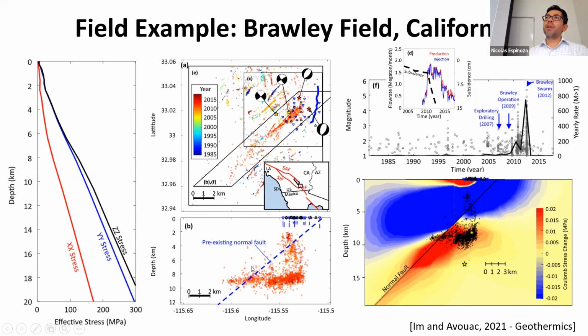So what happened over here? What they show in this paper is that this is caused by the changes of temperature. First of all, as we were saying before, if we have these boundary conditions in which we don't let the rock move in the horizontal direction, but it just moves in the vertical direction, you want to have subsidence. This is thermal subsidence because of the shrinkage of the rock. This is what they observe over here. And second, you have the thermal destressing.